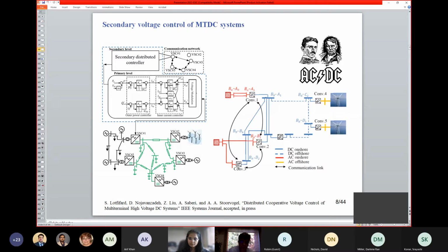Yeah, that is a perfect comment. That is the issue of fault current contribution and also grid strength. There are so many approaches people are following. Some say to oversize the inverters so that you have more current contribution, or to use synchronous condensers, just for contributing to the fault.